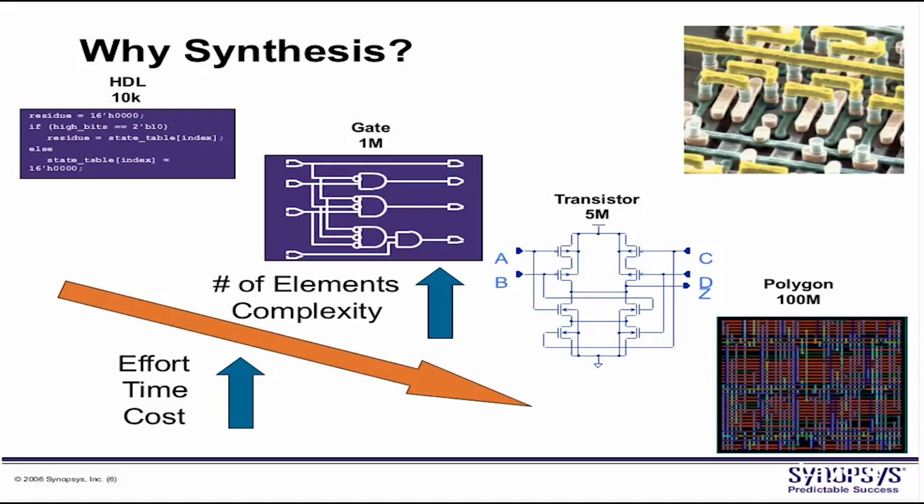Second approach, which is a high level approach: I would write an HDL in Verilog. Let's say in Verilog, I write something like this for the decoder. I use synthesis to convert this into a gate level netlist, and then again proceed for physical design.